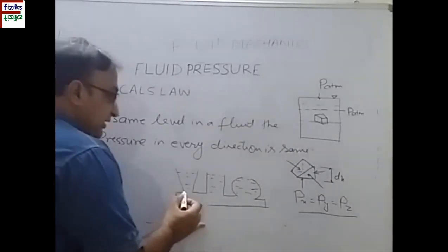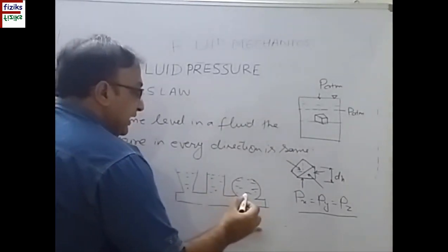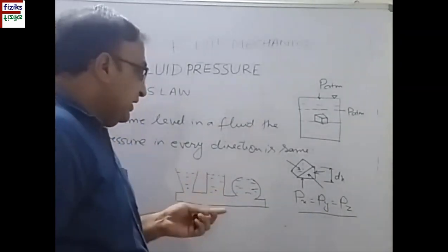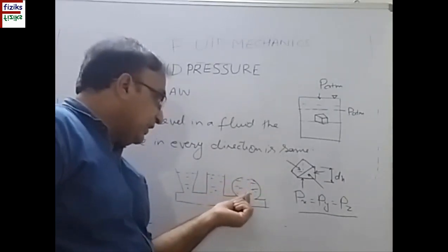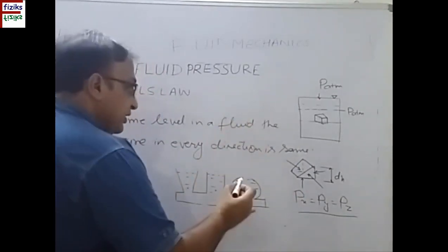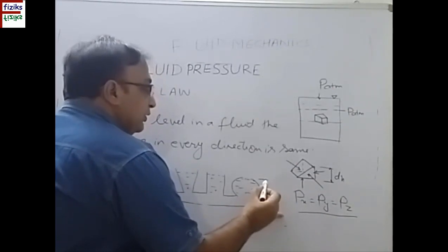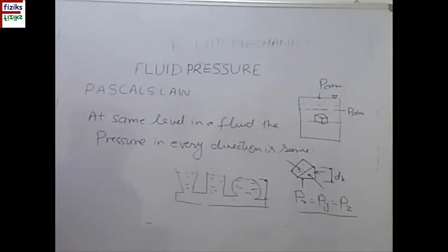Then the pressure at the same depth inside these three will remain same. So we can see that the pressure is force per unit of area. So area here is unit area at the base or at any point at the same depth. If I take this depth to be same for all the three, the pressure will be same irrespective of the shape of these three containers.